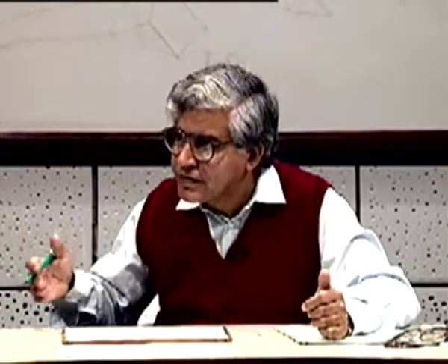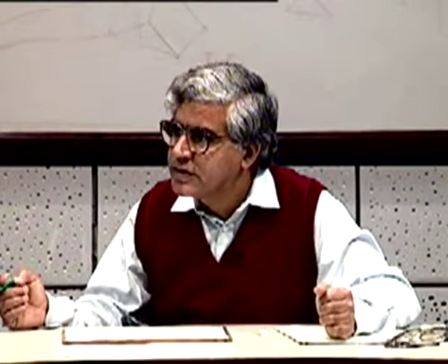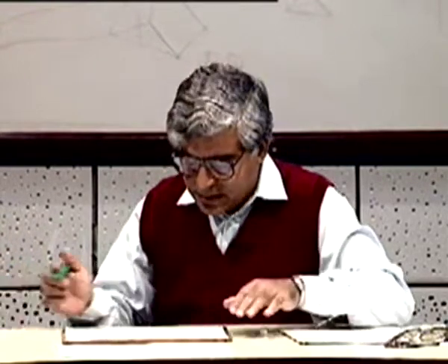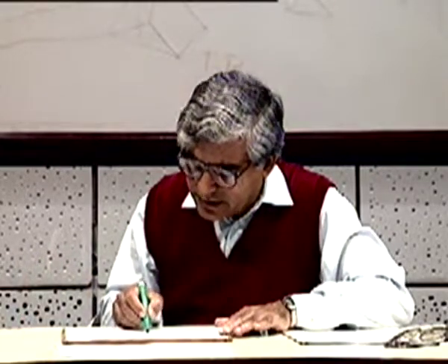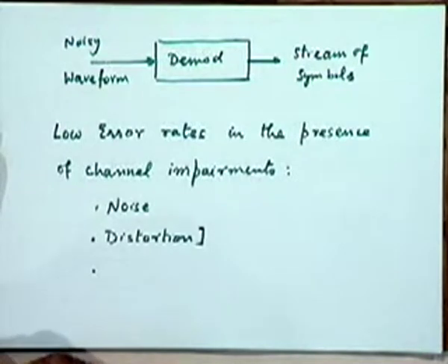Because after all, when you have a nonlinear phase response, that might cause what is called a spread of the signal along time, because different frequency components are coming at different time instants, with different delays, and therefore the received waveform may be a broader signal as compared with the incoming pulse. So as far as intersymbol interference is concerned, that effect is included in this term distortion.